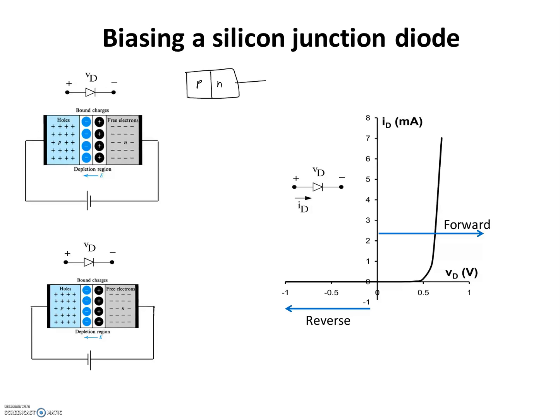If you do so, because the P-type semiconductor has a high concentration of holes and the N-type semiconductor has a high concentration of electrons, the holes diffuse to the N side and the electrons from the N side diffuse to the P side. In the close vicinity of the junction, the electrons and holes combine, and as a result the N side next to the junction is going to be positively charged, and the P side next to the junction is going to be negatively charged.